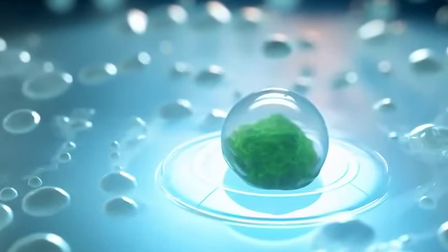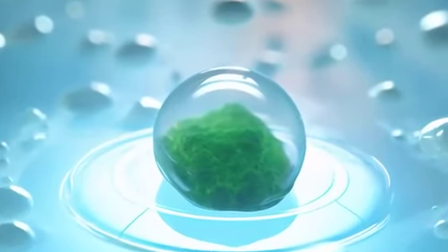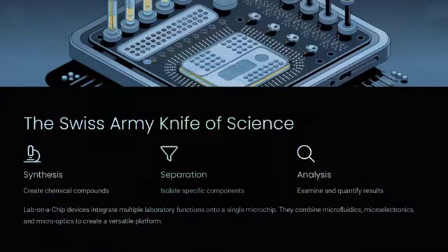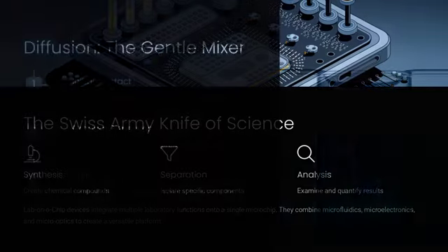At the microscale, fluids behave according to laminar flow dynamics because viscous forces dominate over inertial forces. For instance, two colored liquids injected into adjacent microchannels flow in smooth parallel layers without turbulence, much like cars moving in well-defined lanes on a quiet one-lane road.